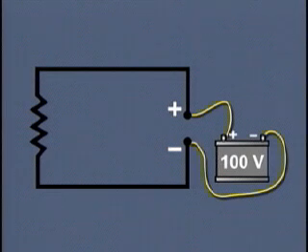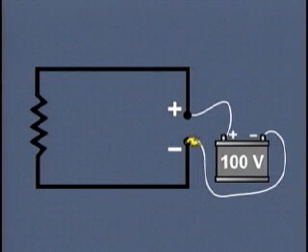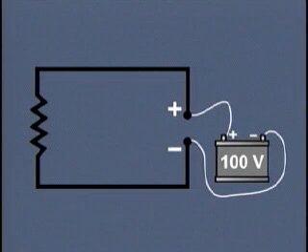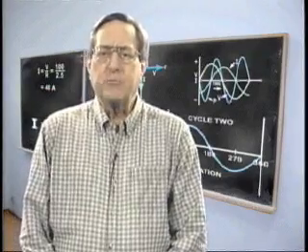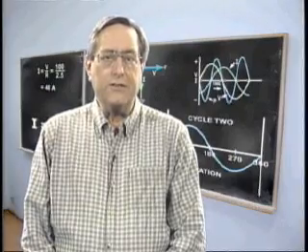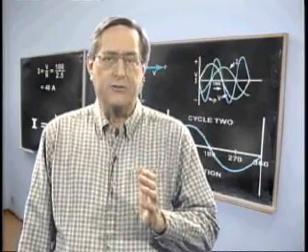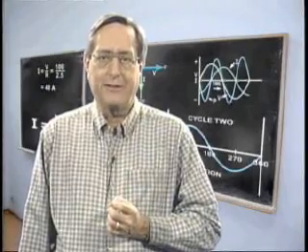One point that we should be aware of is that as we try to make the final connection to complete this circuit, there may be a considerable amount of sparking as the current tries to flow and energize the lighting circuit before we have completed the connection. We are aware, of course, of a similar situation that occurs when we disconnect the circuit when the lighting is no longer required. Now, while this sparking may be considered to be insignificant at these low voltage, low amperage circuits, there may still be a fire hazard or explosion hazard due to gases venting from the nearby battery.